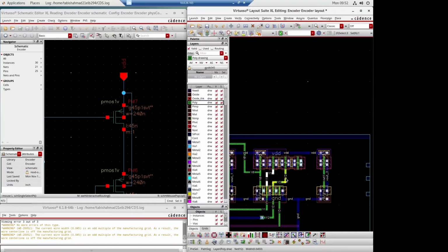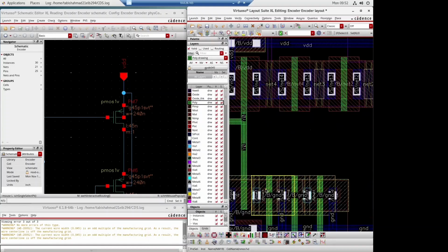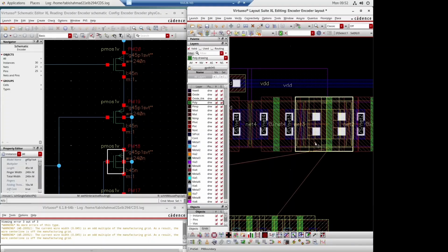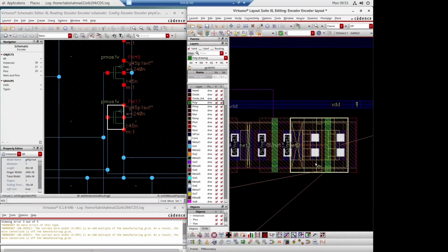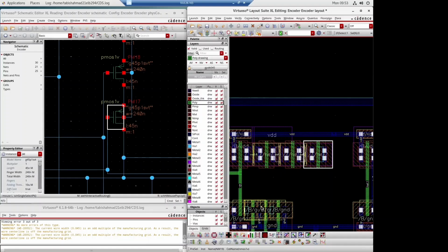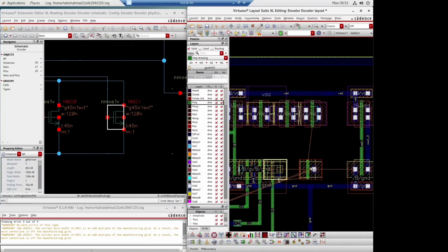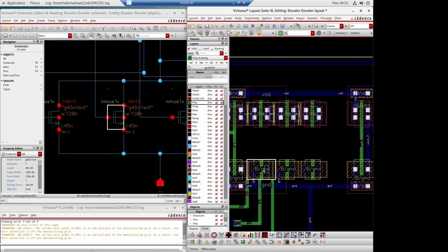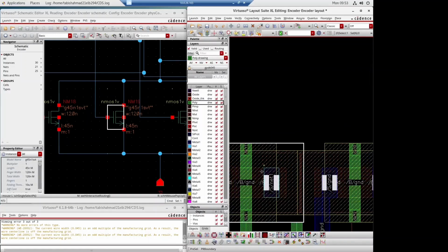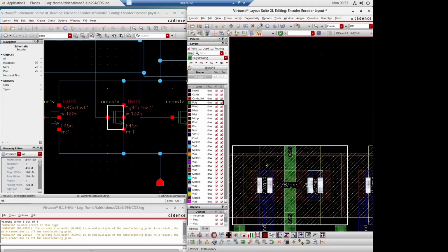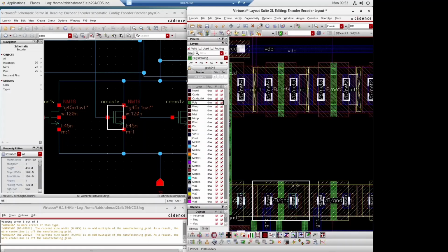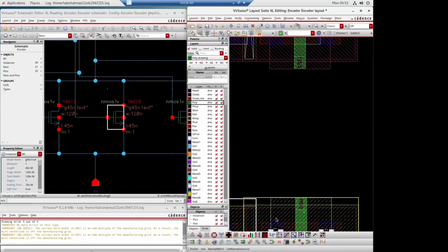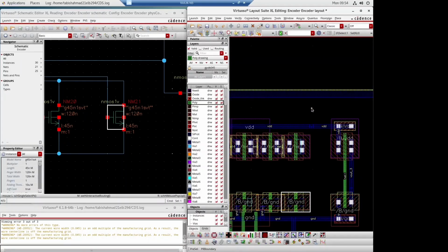Here. Remove these connections. Just drag these a little bit more, just to be sure that no error will come. Now we will drag these NMOS also just below the PMOS in the same alignment. You can see the white and orange line that is coming. I am checking whether it is straight or not and aligning this according to the PMOS above it. So they are aligned now.